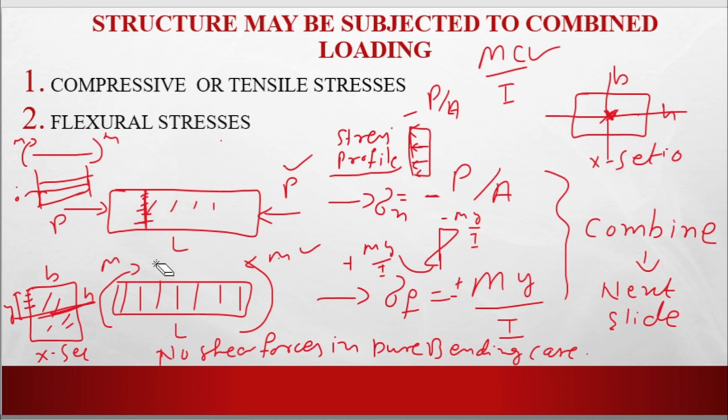So in this case, the stresses produced due to the bending moment will be My by I, and due to the axial force, either compression or tension, the stresses will be produced by P by A. Now we will combine these in the next slide.